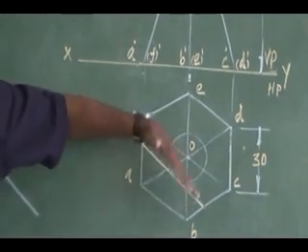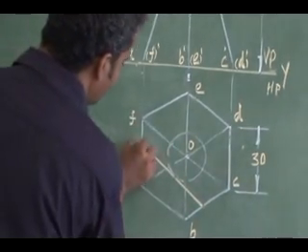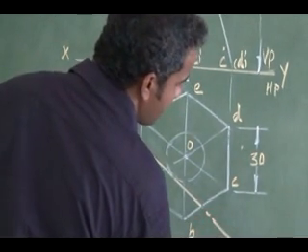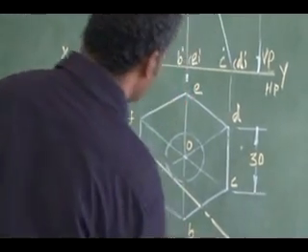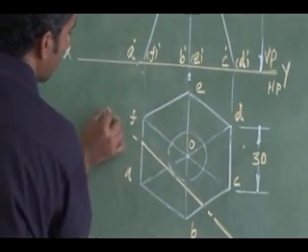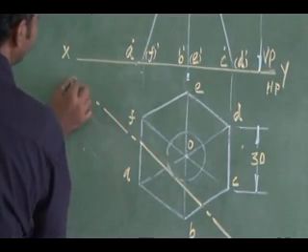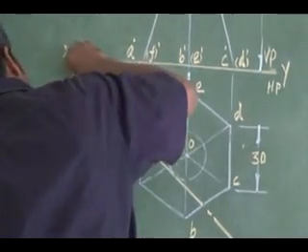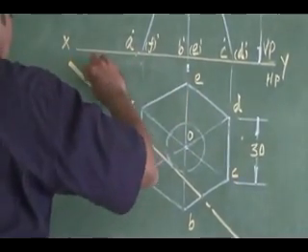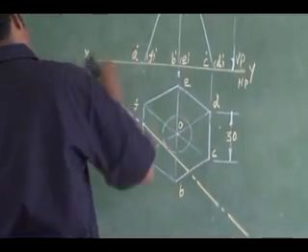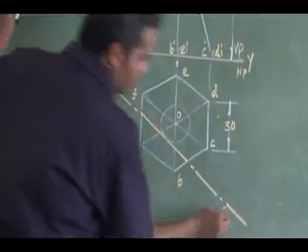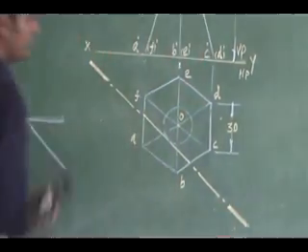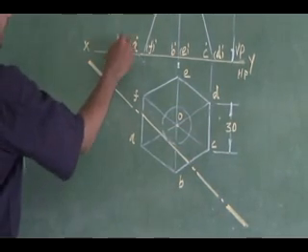If I keep my cutting plane here, this is the way you have to draw your cutting plane, tangent to the construction circle you have drawn. Neatly represent the cutting plane, that is important. The cutting plane should be thickened at both ends, and it is 40 degree.